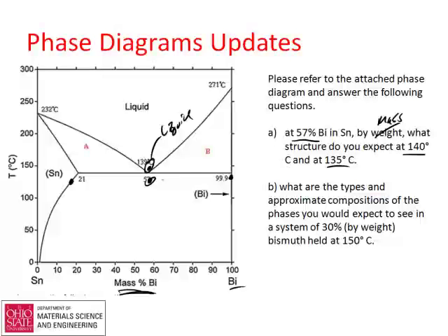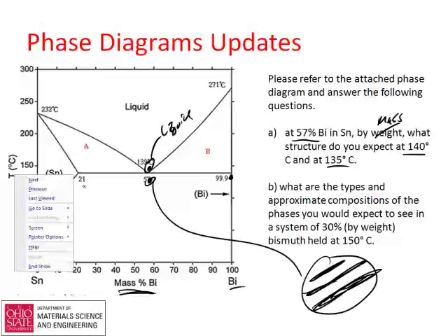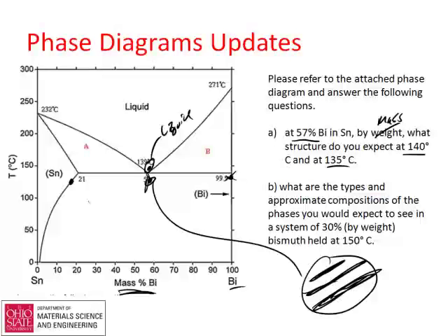And you would get this eutectic structure. So just below this, you've got a microstructure that would be sort of plates of bismuth and plates of tin, and that's what you would end up seeing, and these would be the solutions. And this being about halfway in between, it'll be about half and half bismuth-rich and tin-rich materials.